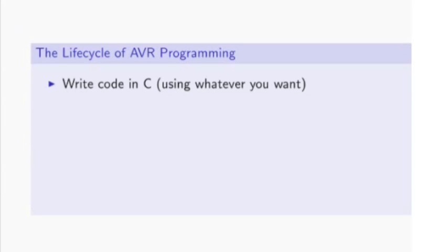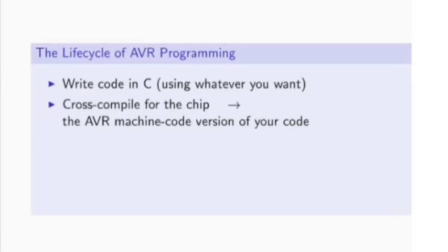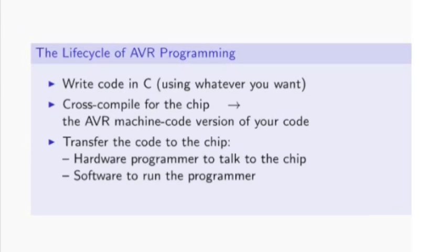The life cycle of writing for the AVR is a lot like it is for the Arduino. You write code, you compile the code for the AVR machine code, you transfer it over, except instead of with the Arduino, where we're transferring it over using a USB cord and a USB to serial adapter that's built on, we're going to need something in between.